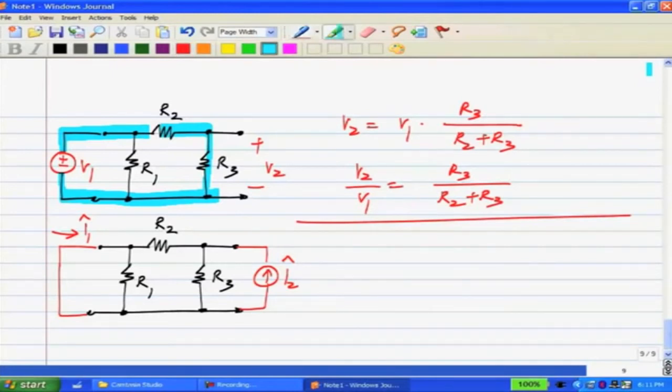And in the other case, what happens? We have a short circuit on this side. So, that means that no current flows through R1. Across that we have a short circuit. So, we just have two resistors R3 and R2 in parallel with the current source. I hope all of you are able to see that. Otherwise, you can see that the terminals of the current source are here, and terminals of R2 are exactly the same, and terminals of R3 are also exactly the same. That is, they are connected to the same nodes.